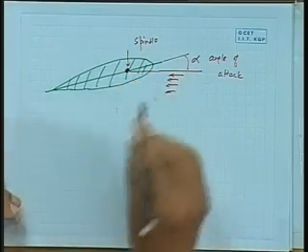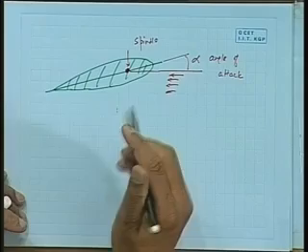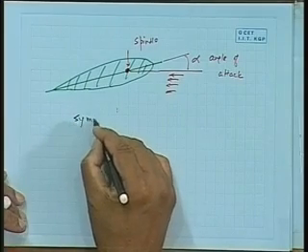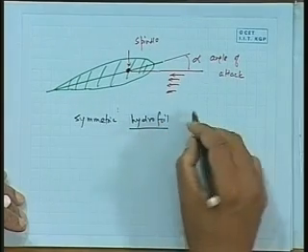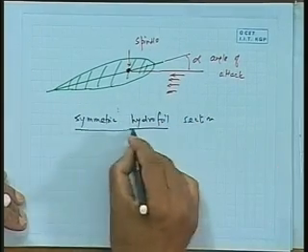You will have a rudder spindle here. Of course, this is a symmetric aerofoil section. Let us use the word hydrofoil. It is symmetric mostly because you want it to have the same performance both sides, not like an airplane where you have an unsymmetric aerofoil, because you wanted the plane to only go up, not down. Okay. Similarly, propeller, you only want force in one direction mostly, therefore it is not symmetric. But in this case it is always symmetric because either turn port or starboard you want equal kind of forces.